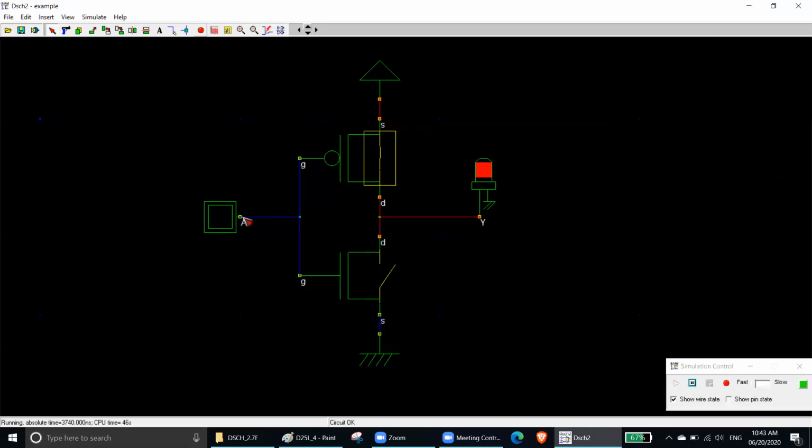So here what is happening? You have given 0, that means the PMOS is on. So current from VDD, that means 5 volt, will come, and after that, current wants to go to the ground, right? Because when current comes from the battery, it wants to go to the ground as quickly as possible. So here, there is one ground at the bottom, but the current cannot go to the ground because this circuit is open. It cannot go in this way because this is an open circuit.